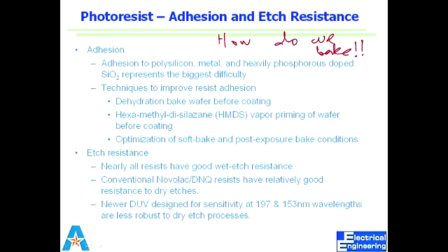If it was quartz, you could put the wafer in your carrier, open the top, remove the lid, and place it like that in the oven. Or you can use boards where the wafers stand and you can put multiple wafers in them, so the hot air can move through both sides of the wafer. So there are multiple ways to bake. That is a very important step, baking. Soft bake and PEB, both are.